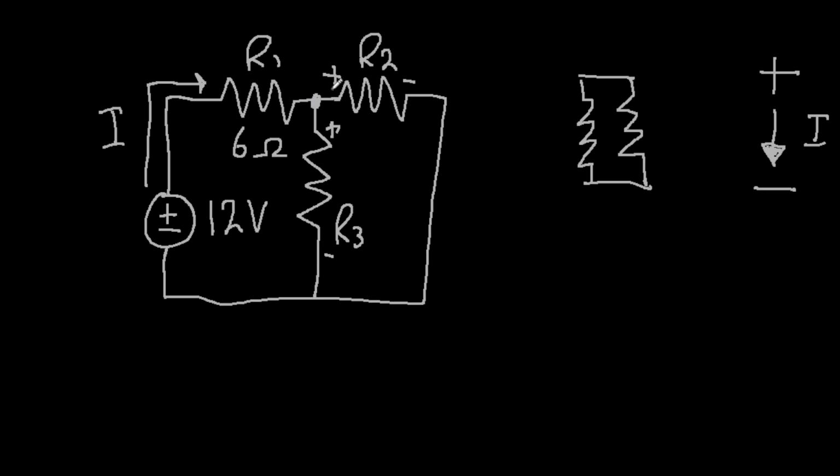Both positive sides connect at the same terminal here. And look at the negative sides of R2 and R3. They connect here. It might not be immediately obvious because of the way it's been drawn, but they do connect here by means of this wire, at this terminal. To help you visualize the flow of conventional current, I will finish drawing the arrows. It will flow across each resistor and through the wires.